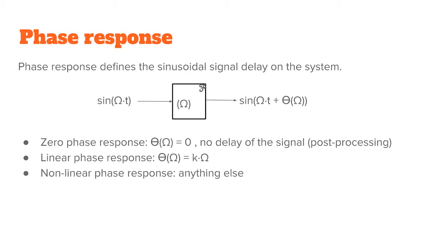3 different cases. On analog systems, you have only one case. It's always nonlinear phase response. You can get near approximation, the minimum nonlinearity on the phase response would be on Bessel filter. Okay, but in digital filters, we really have three different cases. Linear phase response, meaning that the phase response can be described as a constant times the phase angle.